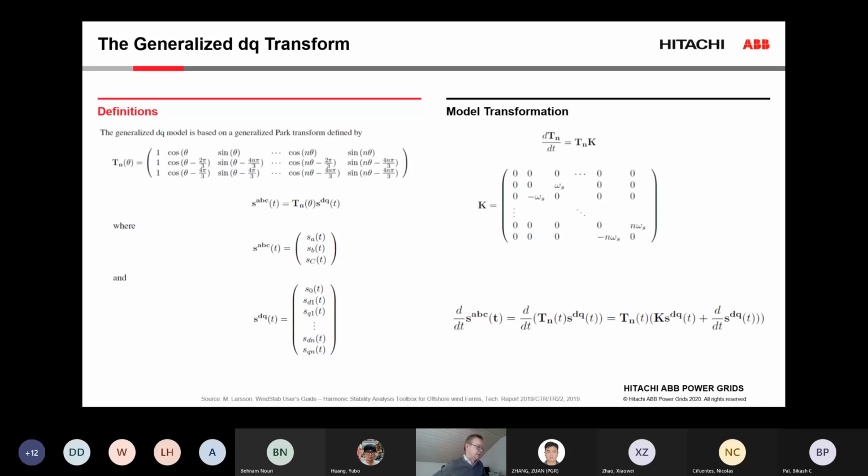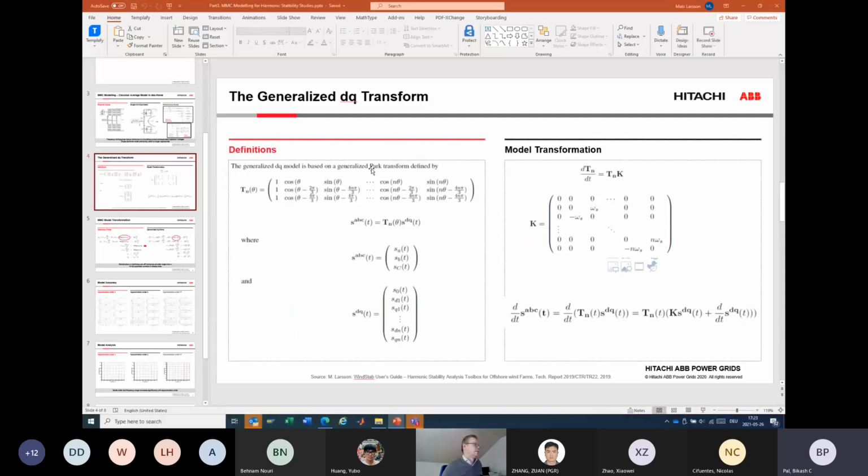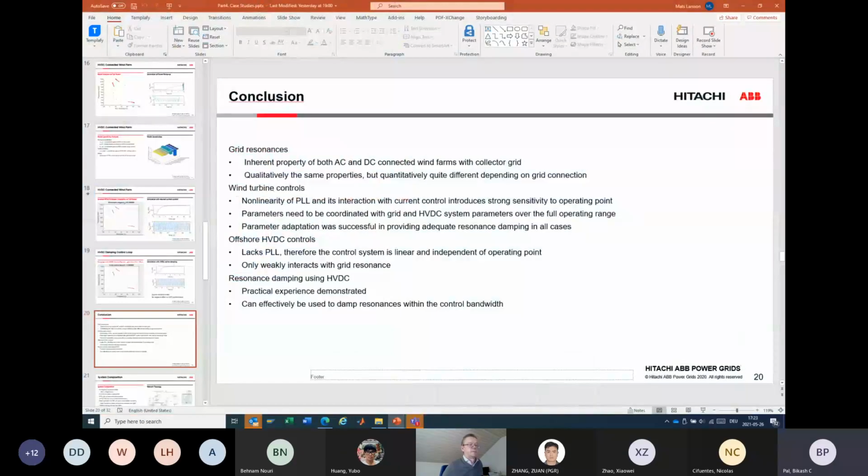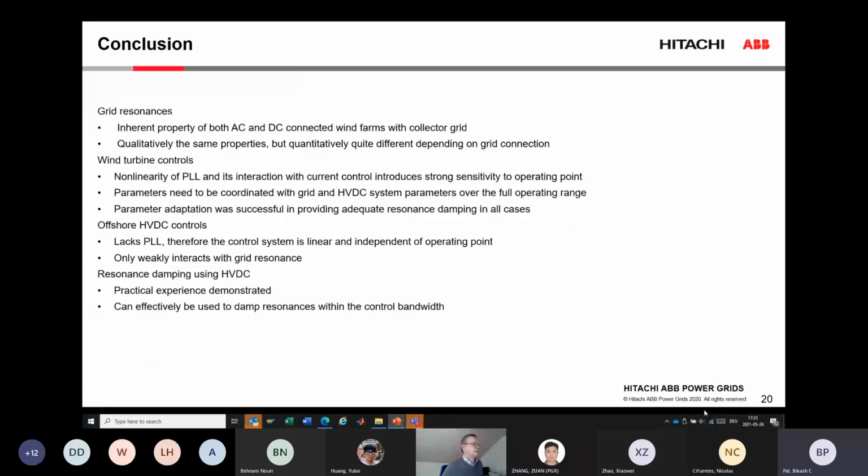And you also mentioned in your talk that you could slow down the PLL by reducing the gain, but then if there is a very stringent fault ride through requirement, voltage response requirement, then this set of converters in grid following mode will not be able to restore the voltage very quickly, right? So there is always a trade-off.